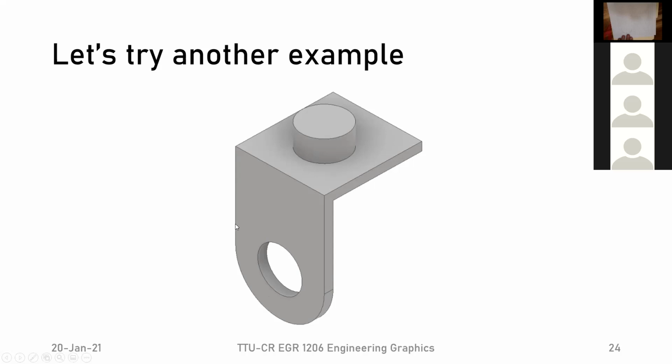So for my inside circle, I chose the diameter to be half of that, so 2. Again, we start at our center point and we draw the 4 points that are easy to draw. We want to draw these points thinly because they're construction points. I'm going to do them a little thicker because I know you have to be able to see them. Now I can kind of see where this circle needs to be, but again, I can go in and do my construction. Because these lines are shorter, I'm going to do it a little abbreviated. So I know my diagonals are going to be like this, and I know my point has to be somewhere in that location.